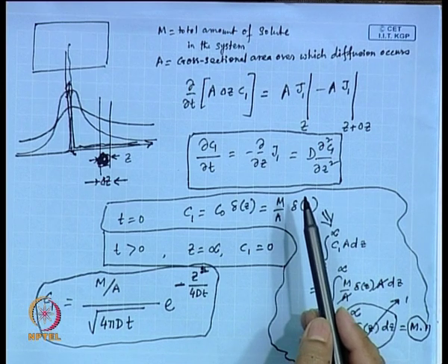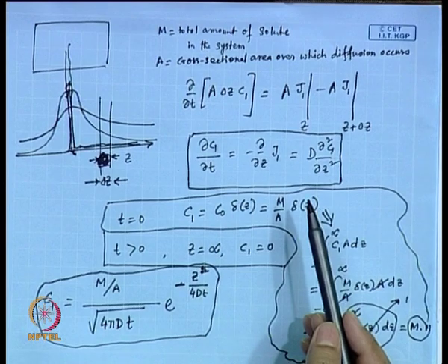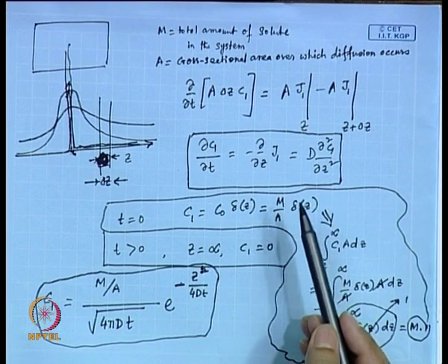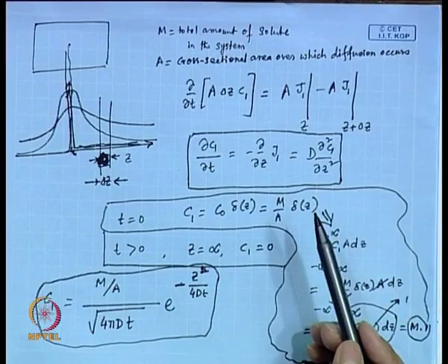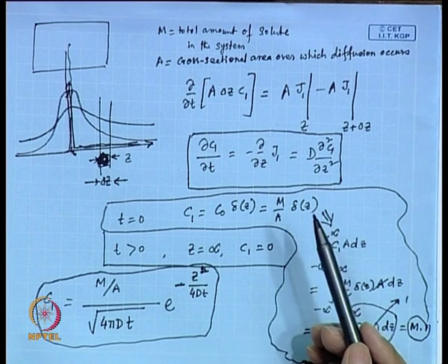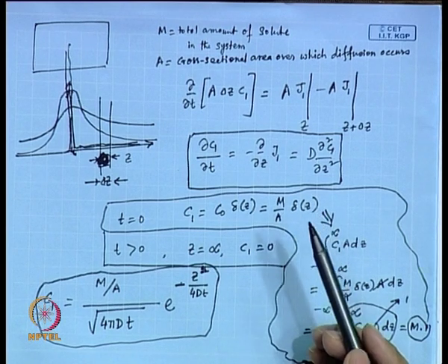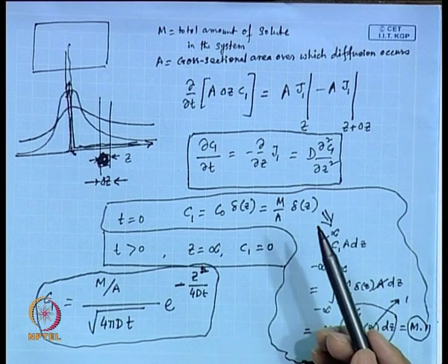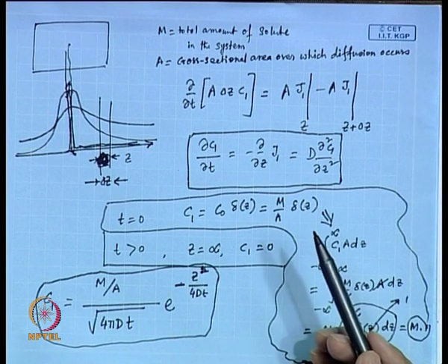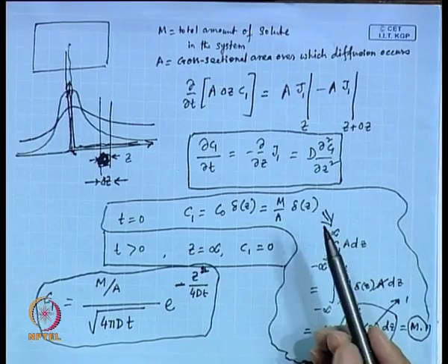Just like the way force balances are done, by the same method a mass balance can be done, and a mass flux. If you are not familiar with this term mass flux, we talk in terms of molar flux, which is basically the number of moles transported per unit time through unit area.